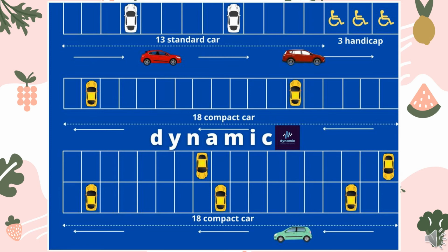This row consists of 13 parking spaces of module W1 for standard cars, together with the addition of 3 handicap parking lots. The placement of handicap parking lots in this row is essential as per local government rules. The selection of standard cars for this row is based on consideration for family customers with kids, which made up about 18% of the total parking lots.